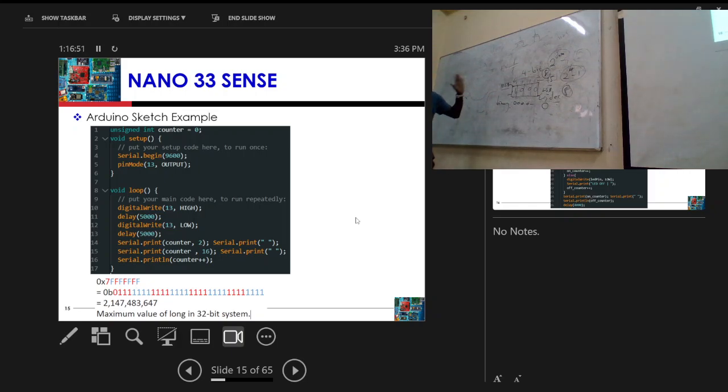So listen again carefully. I say that this is a 4-bit number. We use the MSB, the last one, to identify the number. So that one is out. Once I see 1, everybody knows that the number is negative. If I see a 0 here, you know that the number is what? Positive. So that last bit is out. Now I'm left with only these three bits.